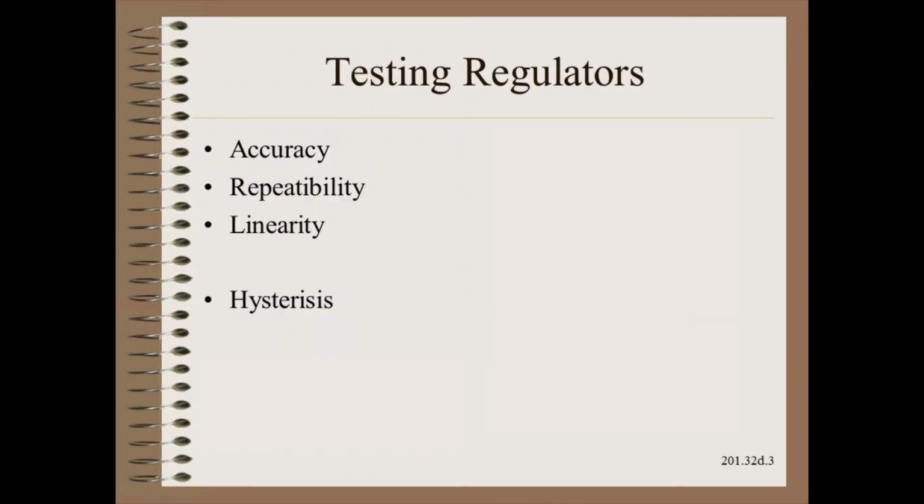As with any instrument, we would be interested in measures for accuracy, repeatability, linearity, hysteresis, and so on. While values might have been given for these quantities by the manufacturer, a valve in the real world may be better or may be worse. We cannot assume that a valve will perform properly whether old or new.